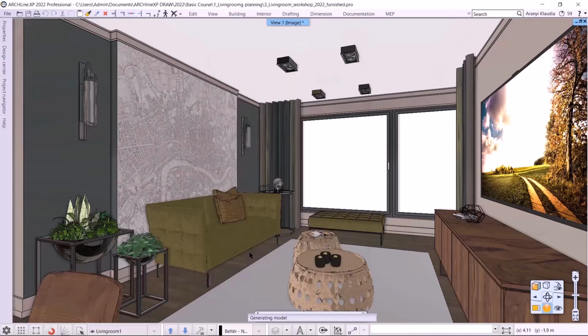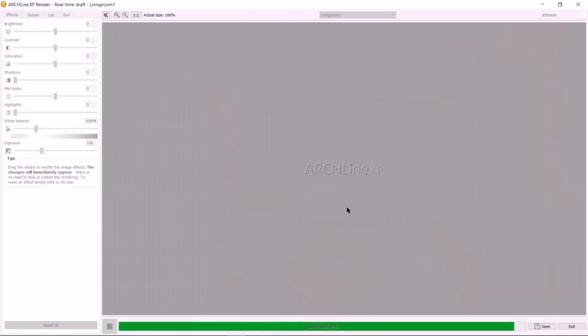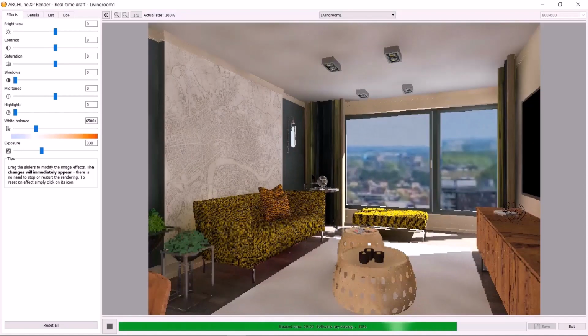The rendering time depends on the processor performance, the available memory, the model size, amount of lights, the quality of the render, and the resolution of the image. This will be covered in the rendering workshop. The rendered image is done. You can see the lights are off, the background is visible through the window, and the sun is shining in. It's the lowest quality image, but the fastest render. For customers, it's worth choosing a much higher quality render type. You can save the image here.